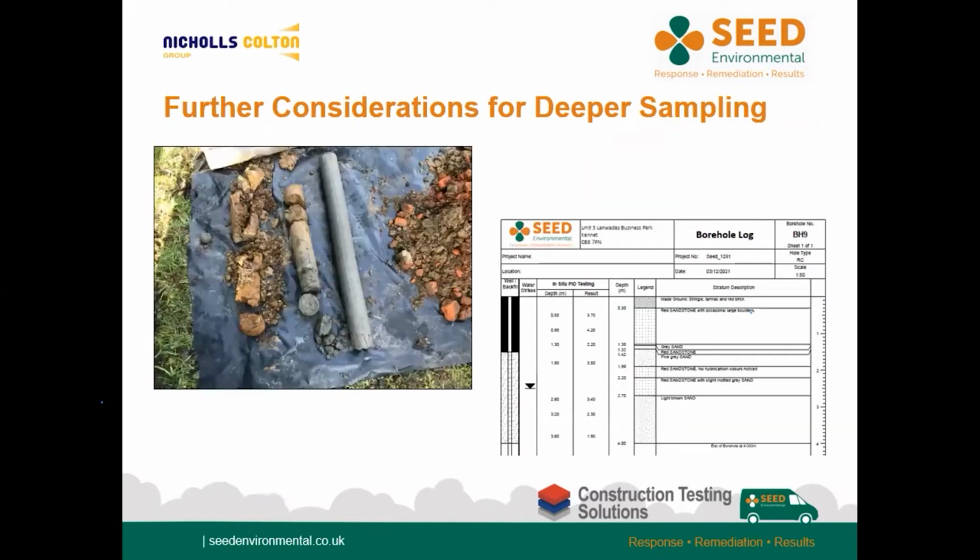When planning to mobilize a drilling rig to site, it is also worth considering more than just the collection of soil samples. If you are anticipating groundwater, do you want to install a monitoring well? And if so, how large a well do you require? If you think the site may require some later in situ remediation, you may want to consider a larger diameter well so that it can be used as part of any future remediation strategy. Although not specifically needed for your soil sampling regime, installing a monitoring well network during this phase of works could also present your client with a future cost saving.